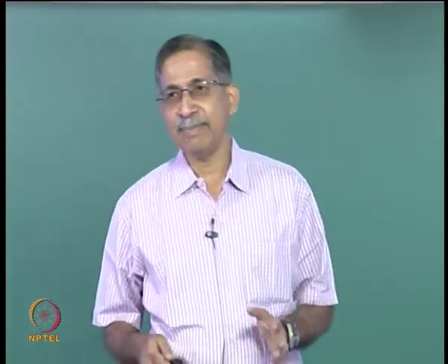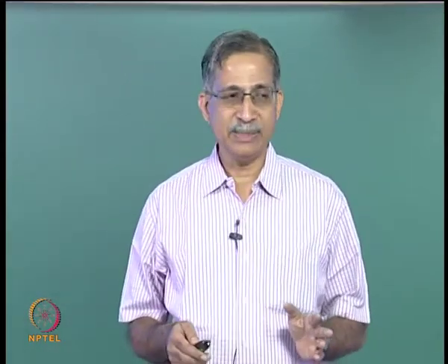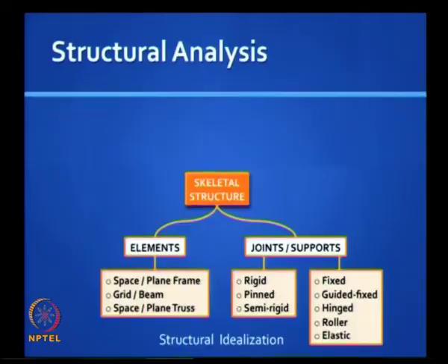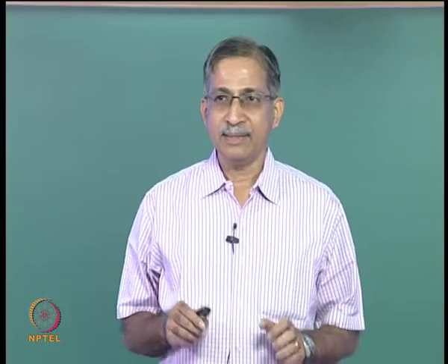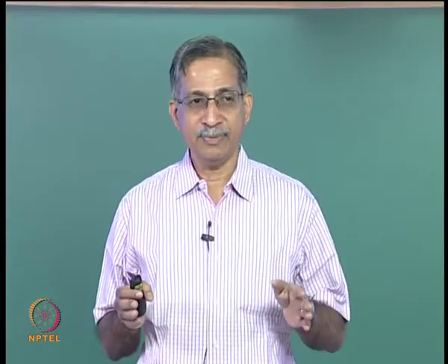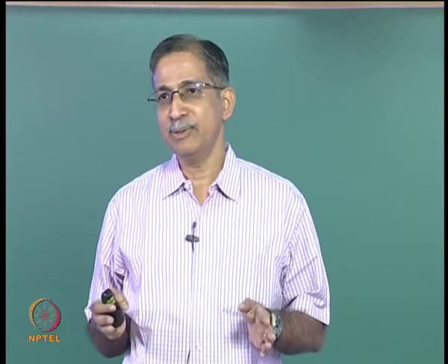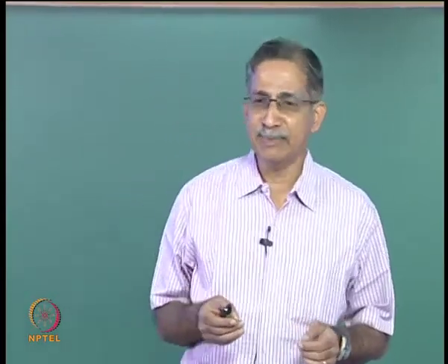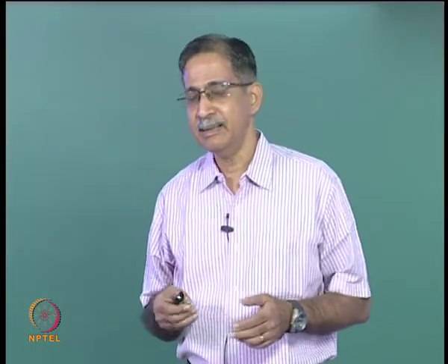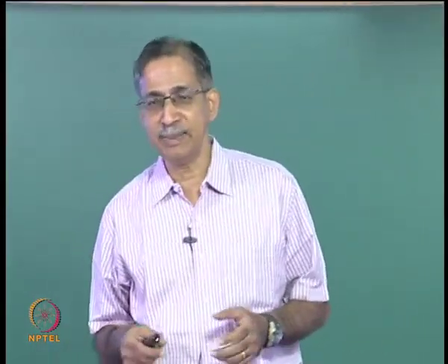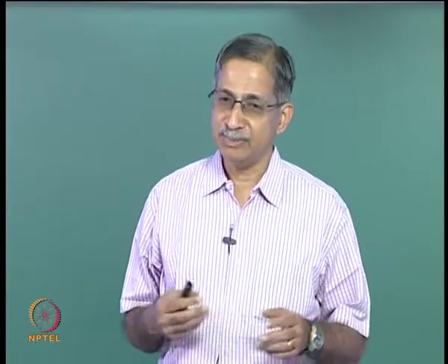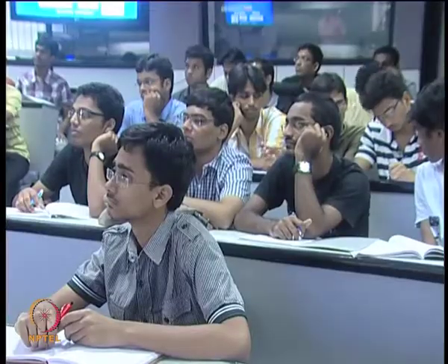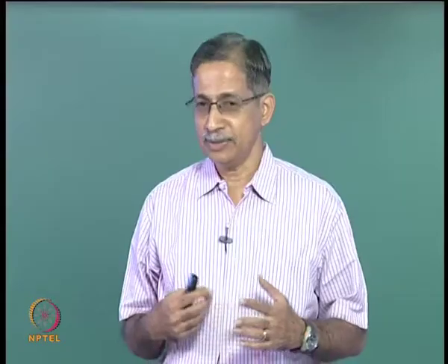So let us come back to the big picture. We are dealing with a structure. We are actually dealing with a model of a structure. In this course in structural analysis, our structure will be a skeletal structure. We are removing the spatial elements from the structure. The structure is made up of elements, and the elements could be space frame elements, plane frame elements, grid or beam elements, truss elements. Of course the most generic is the space frame element. All other elements are special cases of that one element, and the elements are interconnected with joints.